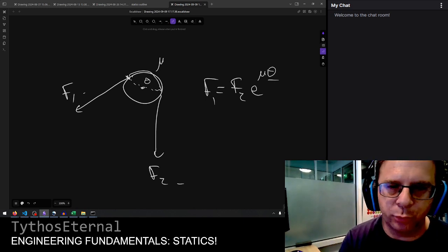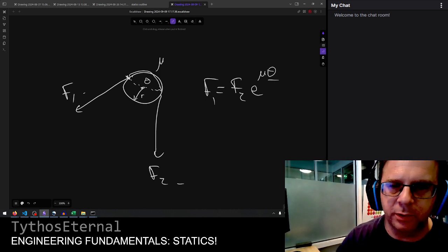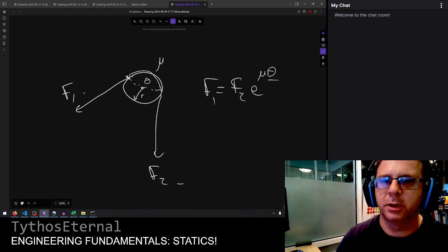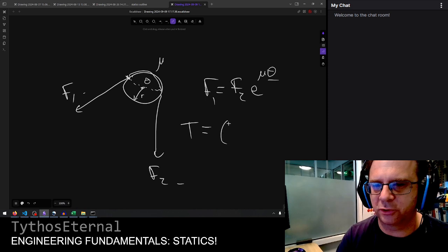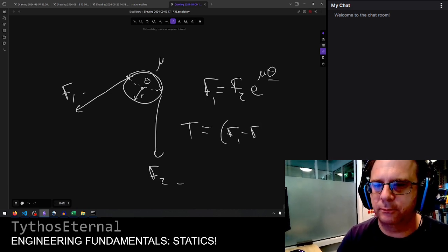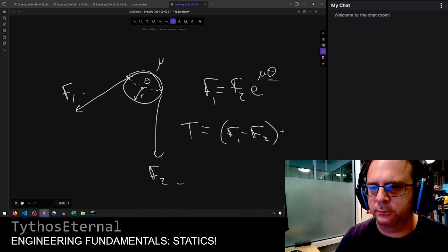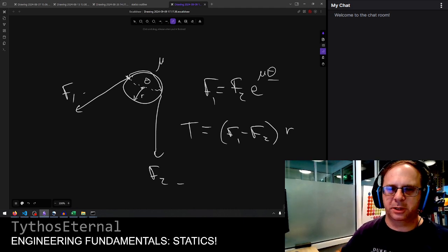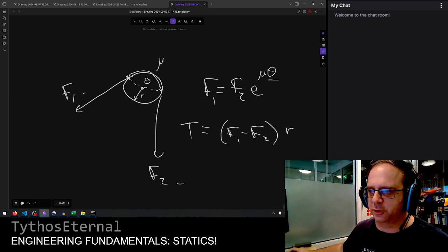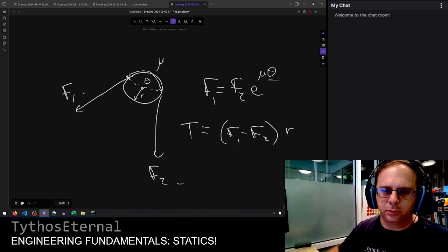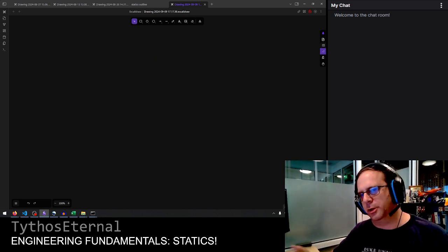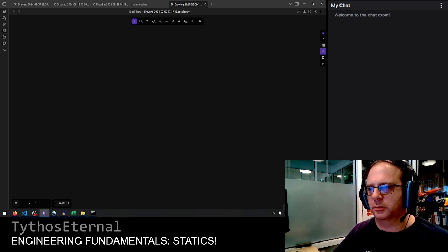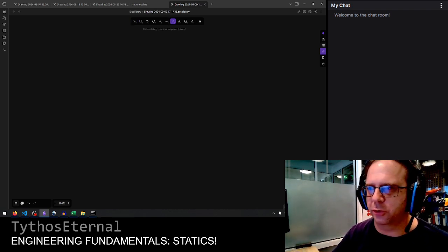And then, of course, given the radius of the pulley and the belt, we'd then be able to say, okay, the difference in forces is actually what goes into the torque that's being applied to that wheel at the moment, that the wheel is experiencing or applying. So we can start to model even simple things like pulleys in ways that are a little bit more interesting and a little bit more kinetic, even just with basic friction models.